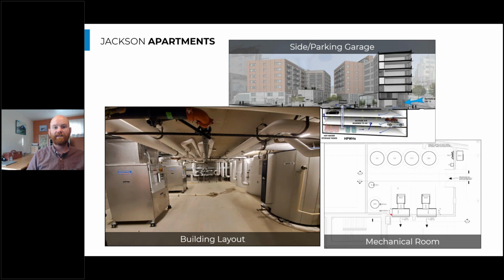And that air is drawn into the heat pumps. The heat pumps take the heat out of that air. They discharge cool air back out of that mechanical room towards a garage exhaust fan system, which is sitting right about here. That's operating continuously. So that cooler air is then taken out of the building and exhausted as garage exhaust air. This allows the heat pumps once again to run all days of the year to provide heat to the system, and really increases the overall efficiency of our commercial heat pump water heating system here, because we can meet that load on those cooler days.